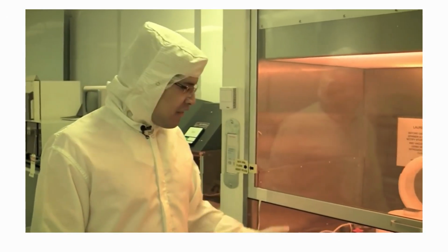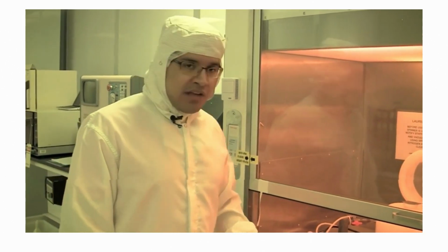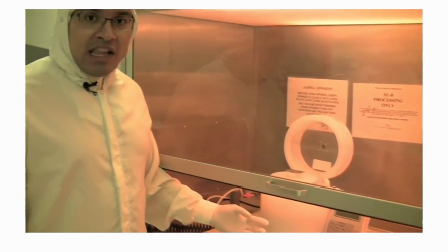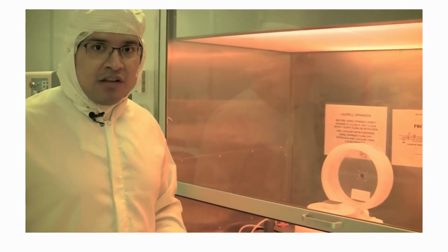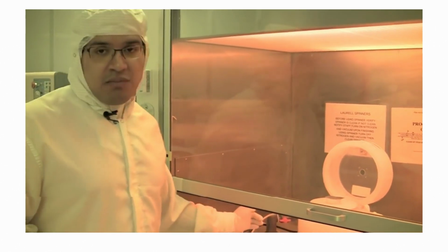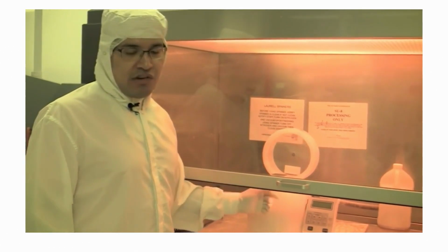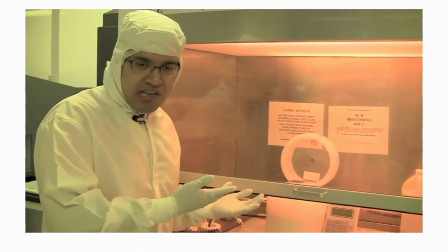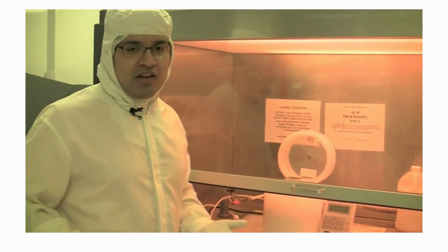We want to make sure that these are followed rigorously. Now, the reason why this is so important is for two things. The spinner itself uses an electric motor which can be the source of ignition for fires. So if these are on, the vacuum's on. And if the vacuum's on and you don't clean this adequately, it's going to suck in photoresist. Most photoresist is flammable. So if the wrong condition happens, maybe a spark, the whole thing can ignite, and that's not good.